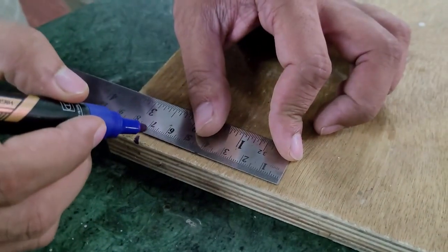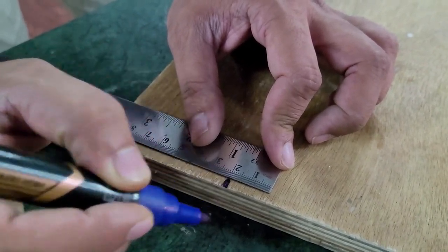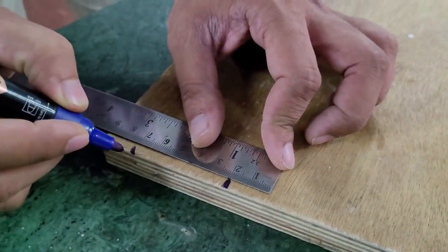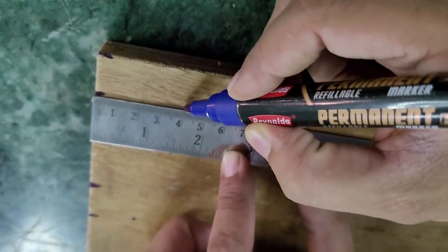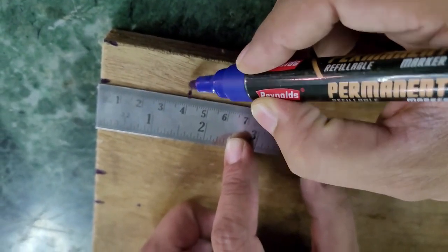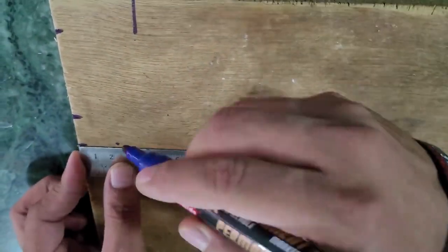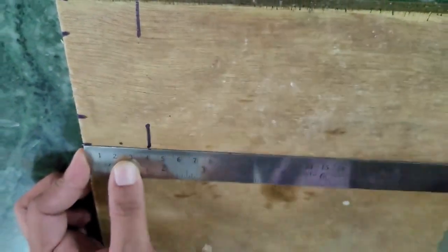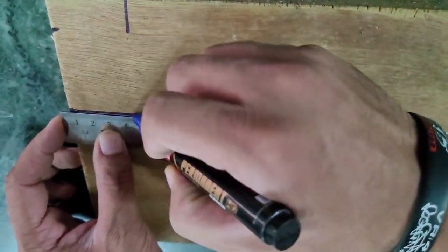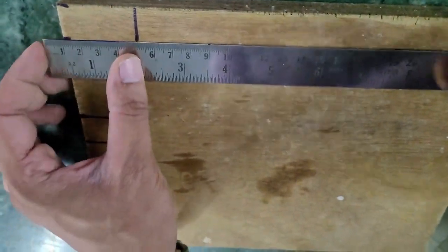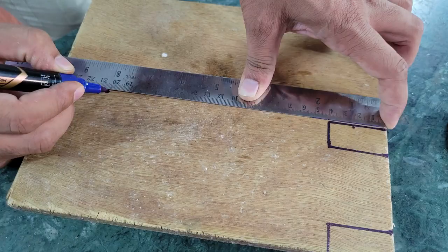This is the dimension. So 20 millimeters from either of the sides and 50 millimeters. So total is the 90 millimeter. You can see in the figure. Let's mark 40 millimeters from one edge, and now let's draw the lines as per the marking. You can pause and see that base plate drawing.